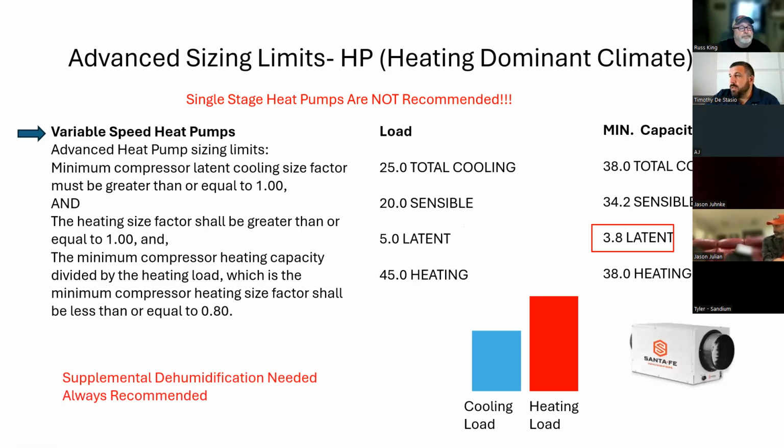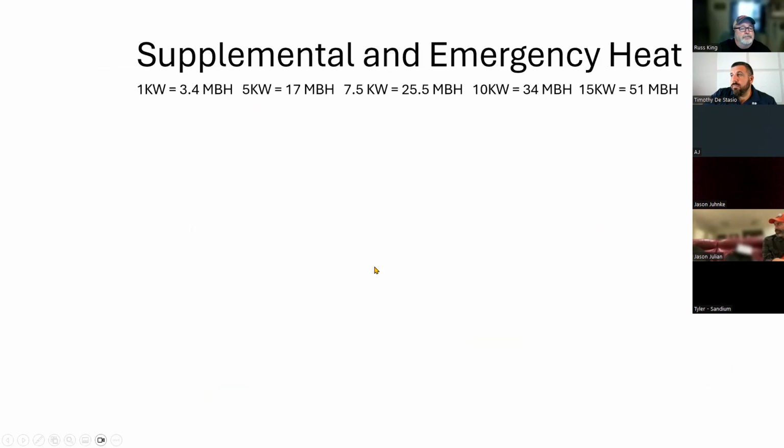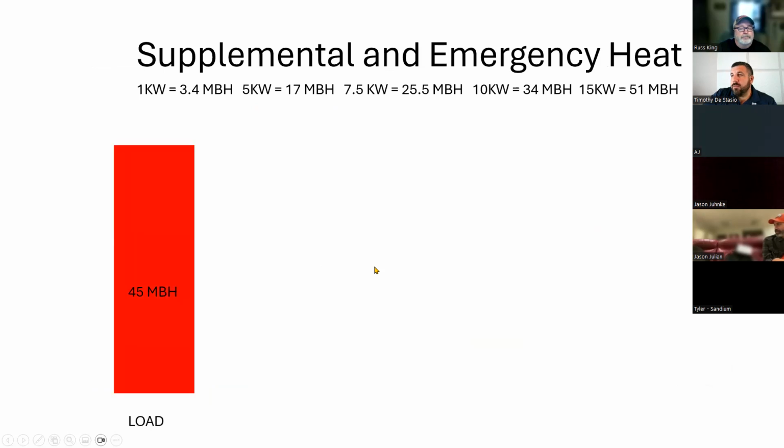And just when we are starting to convert gas furnaces and ACs over to heat pumps, we're going to have to put in a larger tonnage heat pump than the AC unit that we took out. And the flip side of that is that when that heat pump goes in AC mode, it may not be able to turn down to the point where it can remove the latent load. In that case, dehumidifiers start to become our reality. And that's just the best I can do with explaining the situation with cold climate heat pumps and Manual S and their attempts to address that.